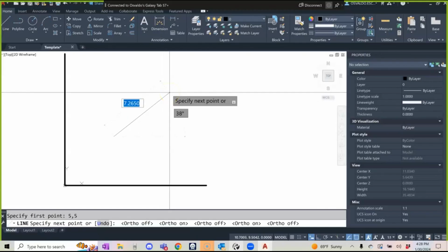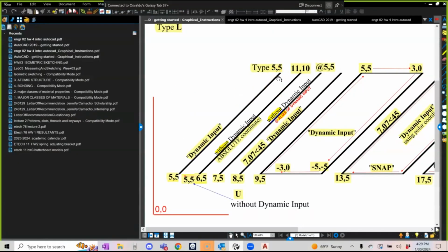The next thing, remember, is to activate dynamic mode. Dynamic mode is a synonym for using relative coordinates. From wherever I am, I'm going to move delta X and delta Y. Where I am is 5,5, that's my current location. Then it says to move 5,5, so delta X equals 5 and delta Y equals 5. Does that make sense? This literally becomes my relative point. It's telling me to move 5,5 relative to my current location, which in this case is 5,5.